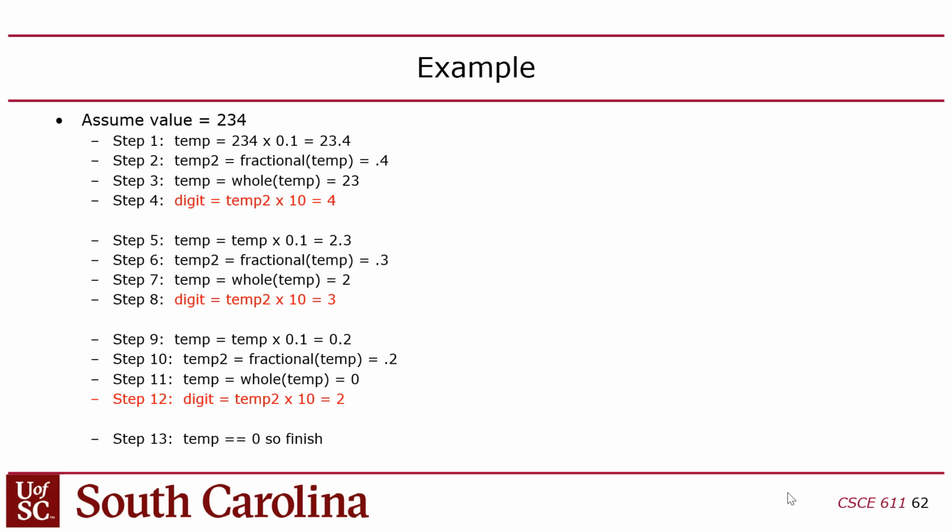So this is simpler. Remember, this is simpler than the program you guys already wrote in Lab 1 because you don't have to worry about taking bits and recombining and shifting across 2 registers. All you have to do is do a multiply HU between a number and 2 to the 32nd divided by 10, right? And that will give you the divide by 10. You guys with me? Right? Very simple. No, you don't have to bit twiddle with this one.